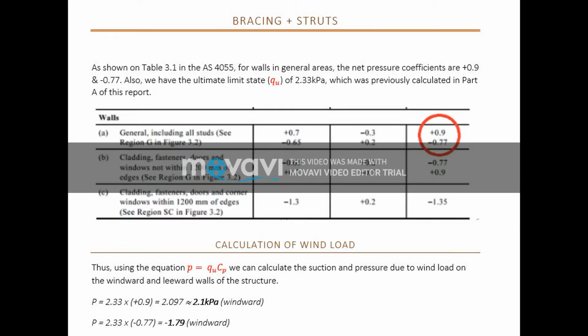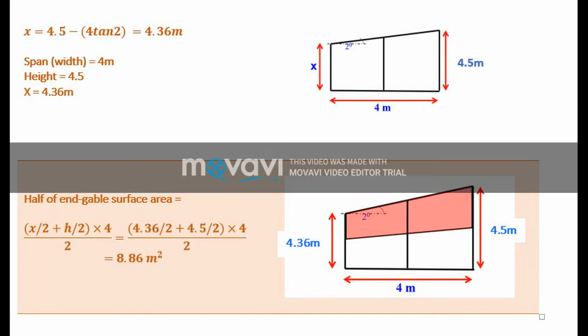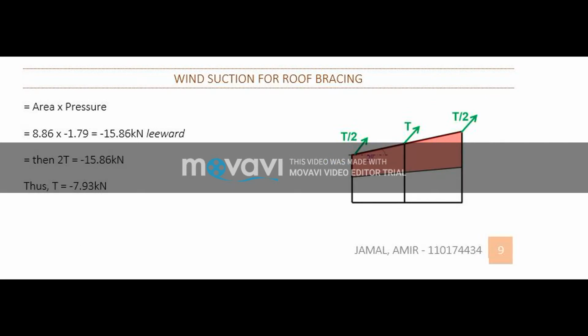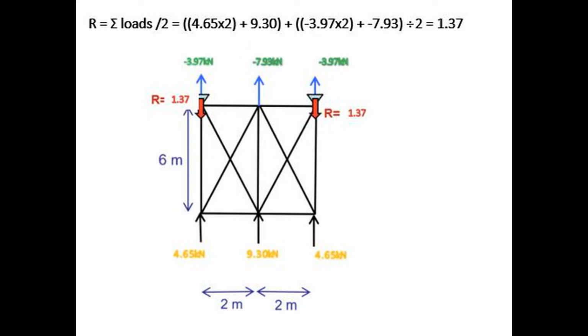Once this task was completed, we then went on to designing and laying out the bracing. Initially, we had to arrange bracing for our shed. After that, we calculated the wind load for the ultimate limit state, followed by the serviceability limit state, and also the suction and pressure due to wind load, using coefficients found in Australian and New Zealand Standards 1170 2002.